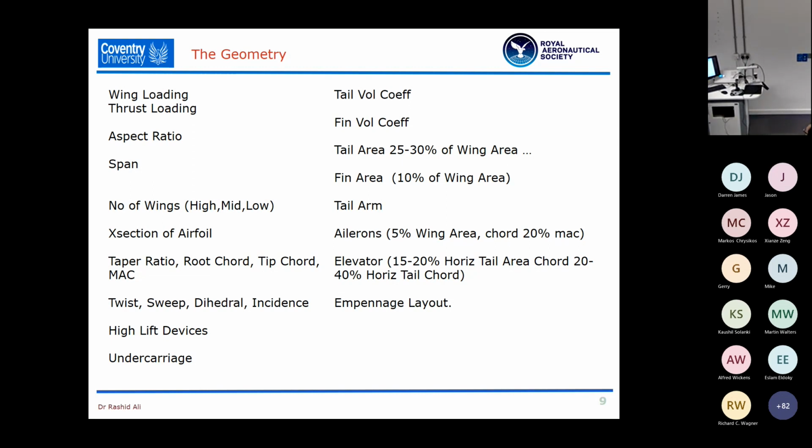So all of those things may have implications from either a piloting point of view or from an engineering point of view. For example, if you have a mid-wing aircraft and you need to get the spar connected from one end of the wing to the other, it goes to the center of the fuselage. So where do you sit? So those are practical considerations that you often have to consider. In terms of then drag reduction and compressibility effects, if you were to go quite fast, then we are looking at many other design features of the wing, such as the taper ratio, the sweepback angle, etc. So they're also quite important from a design point of view.